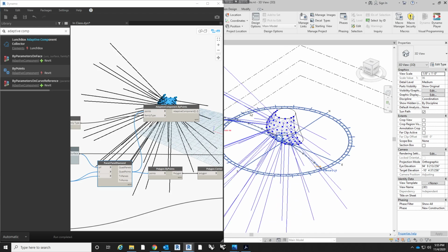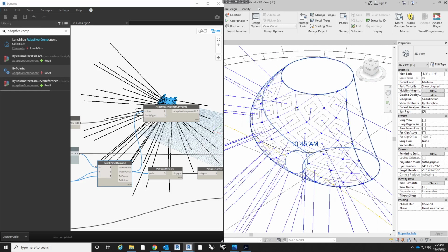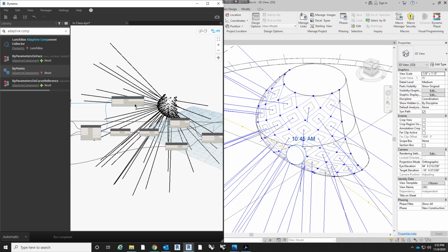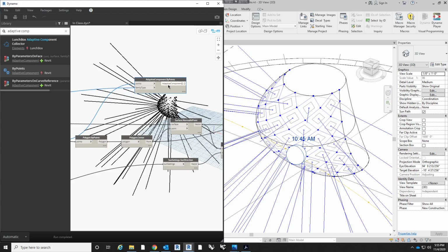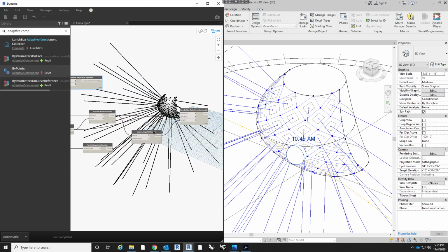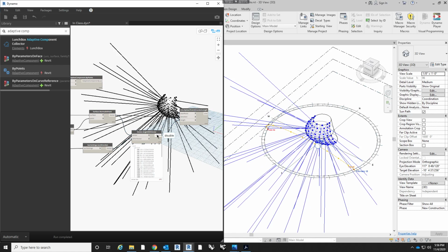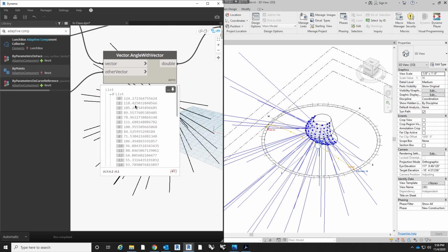And if you go into Revit, you can see that they are then applied to all of the different panels. So with that, we can then utilize the angles, this information here that is corresponding to the vectors that we visualized before. We can use that data to influence our NCP. Now, how do we do that? Well, we can't use these values, right? Because these are wildly larger than what we need. We need something either between 0 and 0.5 or between 0.5 and 1.